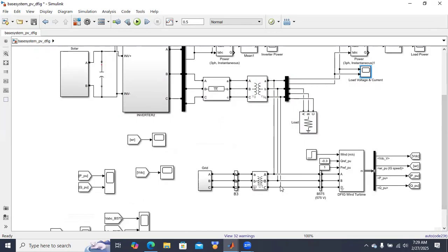It is affecting the DC link of the DFIG. So if the DC link is affected, that is, the voltage is increased, it will affect the components of the rotor side converter and grid side converters. We should avoid this scenario by introducing the Crowbar protection.